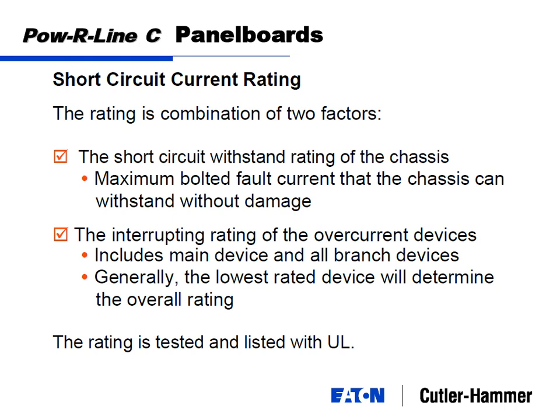And when all is said and done, everything should be turned back on and put back into operation without damage. Asterisk, except for the location where the fault actually occurred. So if your fault occurred inside your panel board, you might have some auxiliary damage, cables and stuff inside there. And generally, the lowest rated device will determine the overall rating, which I'll come back to. That'll be the difference between fully rated and series rated.